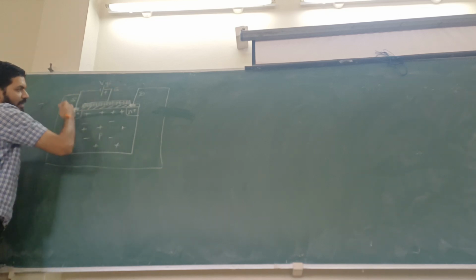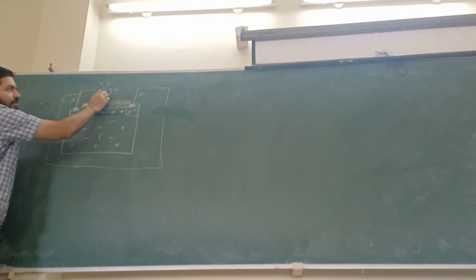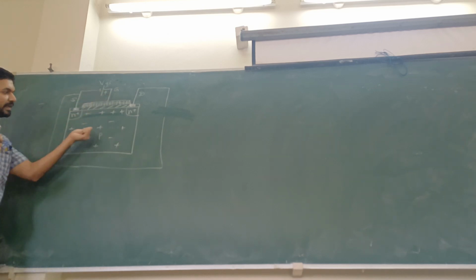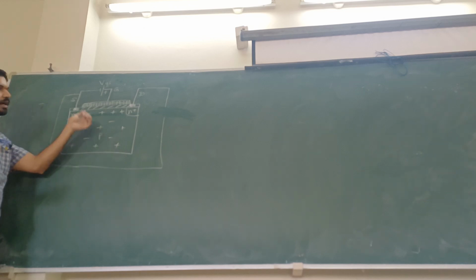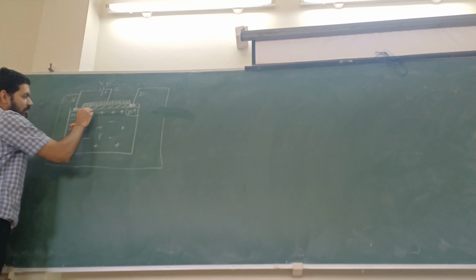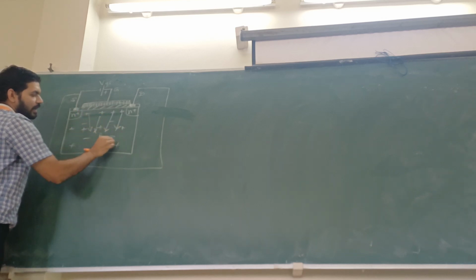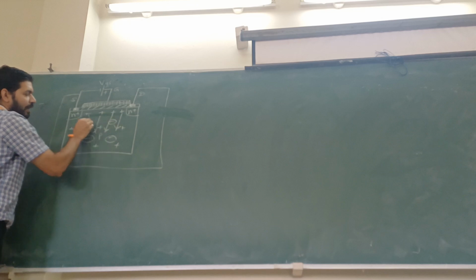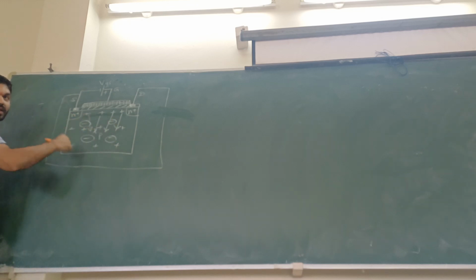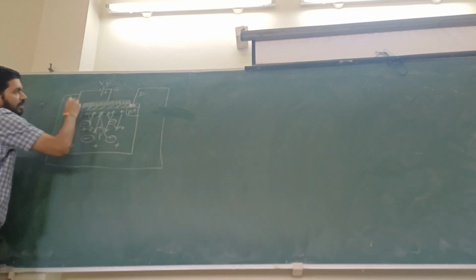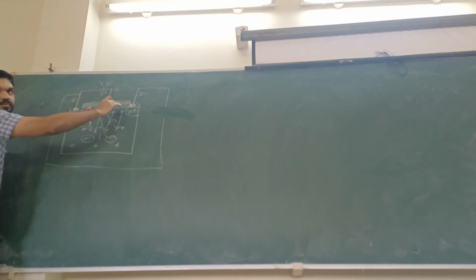Because of the electric field, positive is capable of attracting the negative, that is electrons, and positive repels the positive charges, that are holes. So these holes move away. All the electrons, which are minority charge carriers in p-type, will be attracted near the interface.